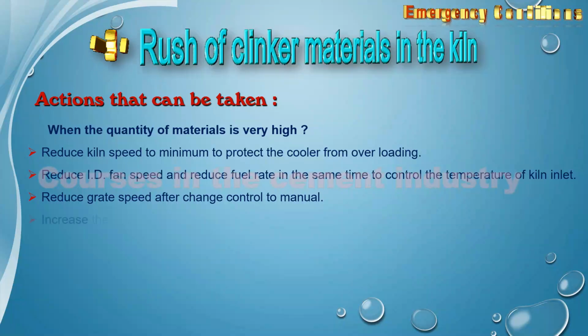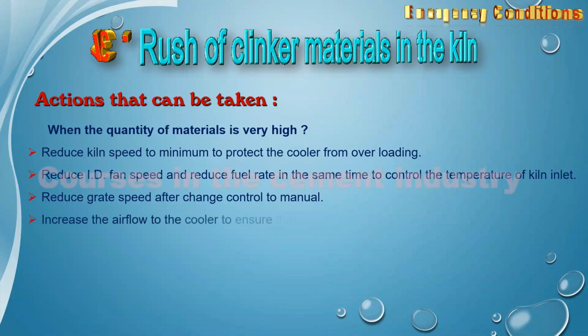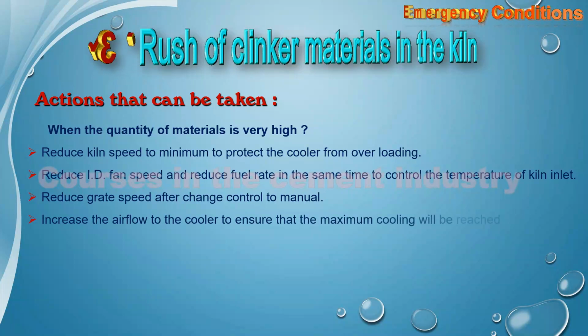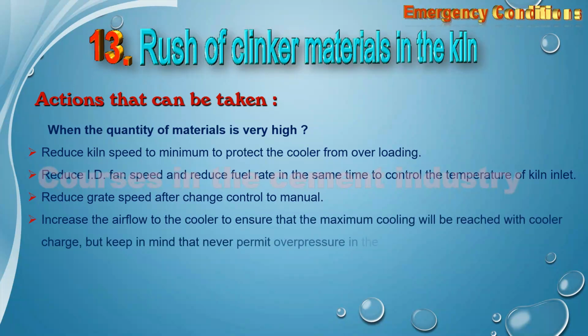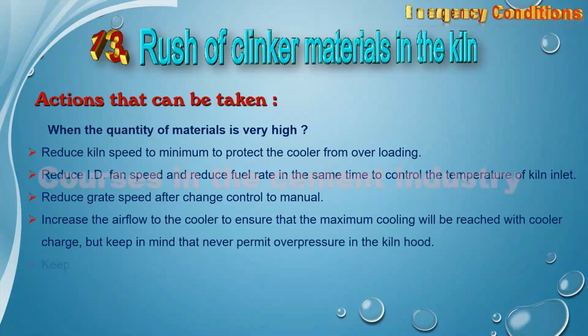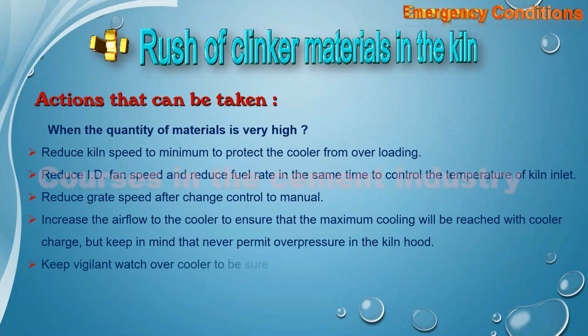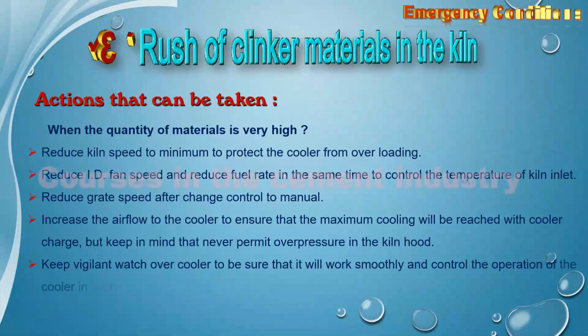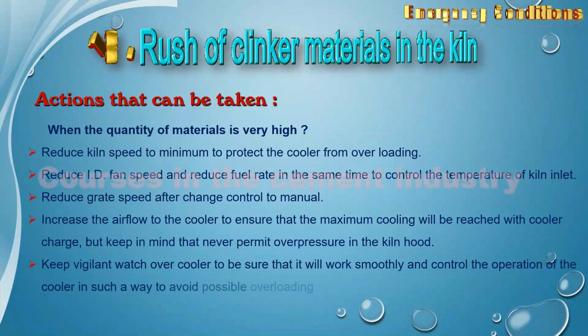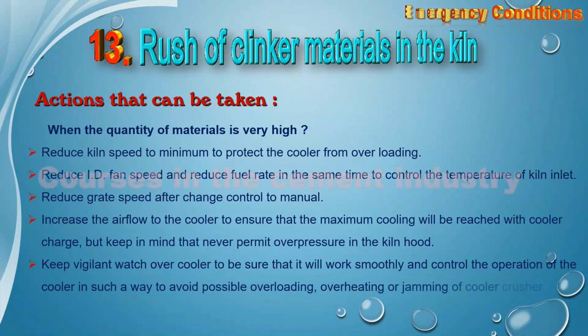4. Increase the airflow to the cooler, to ensure that maximum cooling is reached with the cooler charge, but keep in mind never to permit overpressure in the kiln hood. 5. Keep vigilant watch over the cooler, to be sure that it works smoothly, and control its operation in such a way as to avoid possible overloading, overheating, or jamming of the cooler crusher.